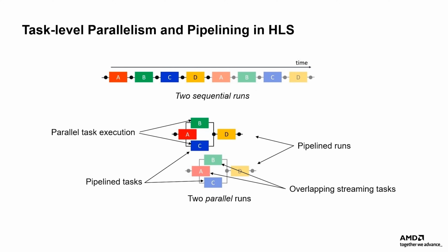Task-level parallelism can be applied to the same example as shown here, thereby increasing performance and utilization efficiency. Here, the throughput is improved because it is limited by the maximum latency among all tasks, rather than by the sum of their latencies. This generally means that at a bare minimum, such software needs to be examined for non-synthesizable constructs, and the code needs to be refactored to make it synthesizable.